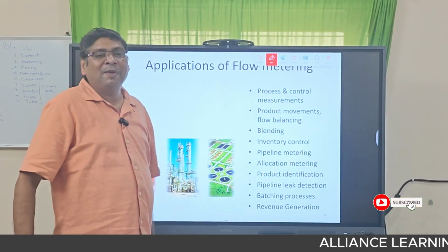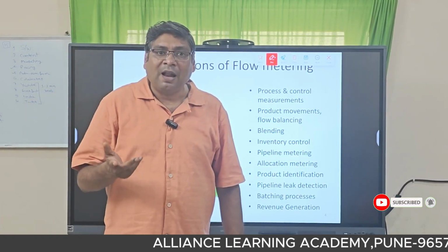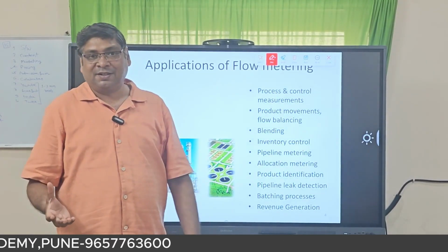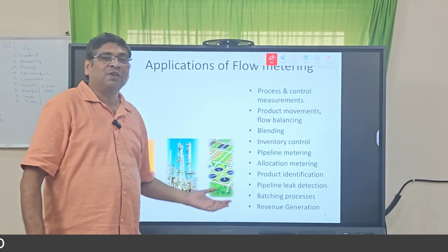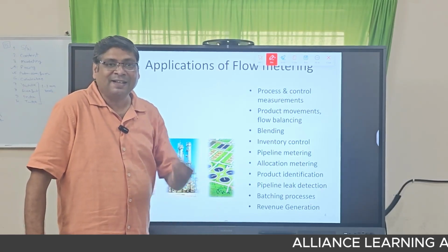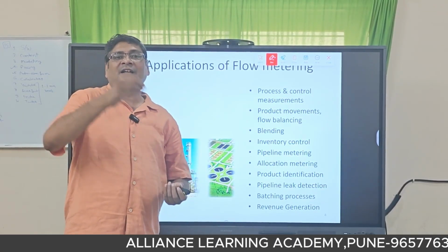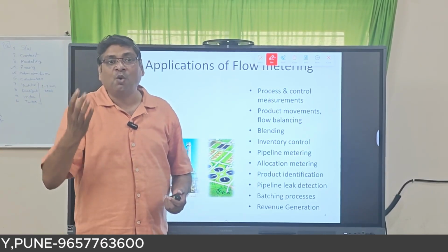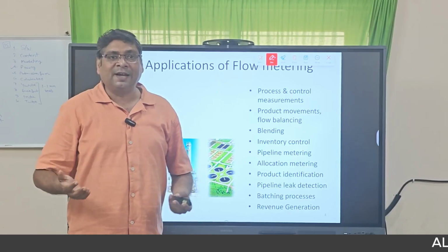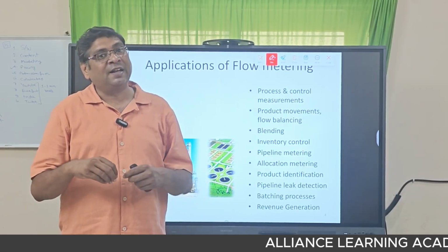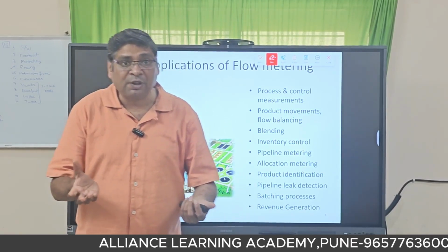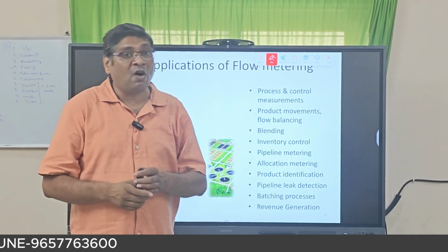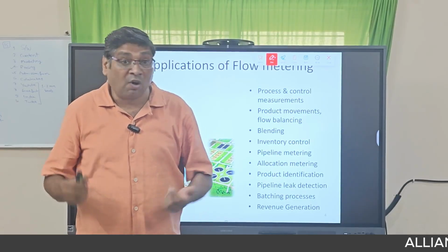Okay, so this is pipeline leak detection. This is a very simple application of any flow meter, and it is the application most commonly used for flow meters. At the starting point, I have a flow meter, and at another point in the section, I have another flow meter, and I am measuring the flow and the total, both values. We will understand if there's any leakage or if any unauthorized people are drawing the fluid or the water. You see the theft of oil and gas also, and in water also.